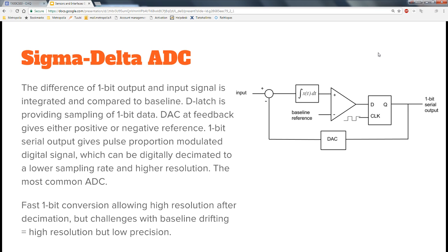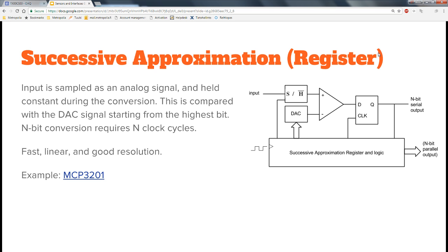But on the other hand, nature works so that if you have some decibel level at, say, 100 Hertz, then the decibels start going down 6 dB per octave. So if you have any music, you can see that there is very little information on the high frequencies. Okay, so that'll be just fine for that kind of application. Audio, excellent. All right, then something in between.